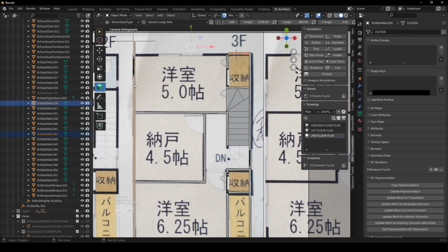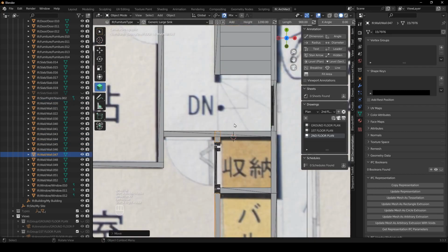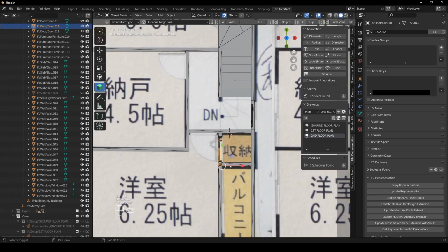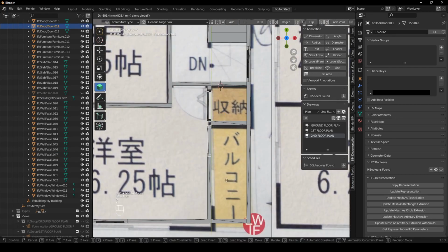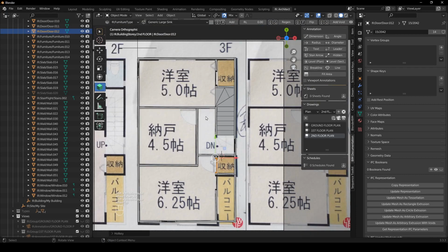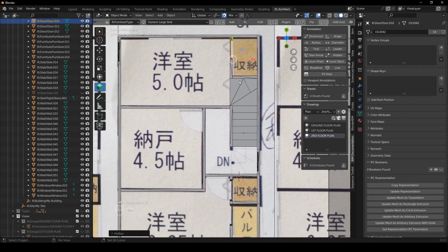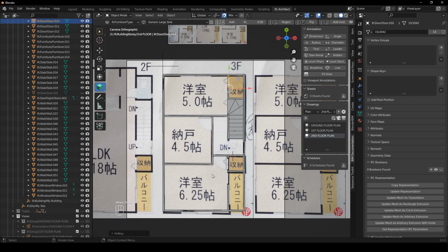I'm going to butt these two walls together, Shift T. And then this wall I'm going to bring all the way to there, Shift E. And this one I'm going to bring in, Shift E. And then I think we have two doors overlapping here. So I'm going to say G Y, G Y, Shift G, and Shift F, so it's opening out. And also this one, Shift F. Okay, cool. And then I think I just want to move this door G Y over there and say Shift G. And then I'm going to go into 3D so I can have a look at this quickly.